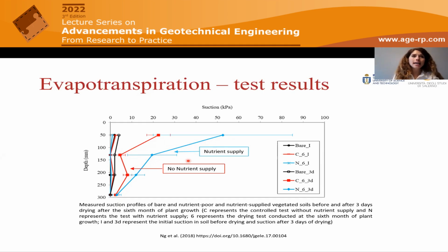So we may say that by controlling some soil conditions, we may achieve a better root development and thus a better response also in the soil hydraulic behavior. So this can be used to our advantage, because whenever we are going to use plants and design vegetation-based solutions, assessing these different effects that vegetation can have on soil, we may also decide to artificially change the root features to our advantage in order to gain a better performance also in the unsaturated zone for the slope stability.